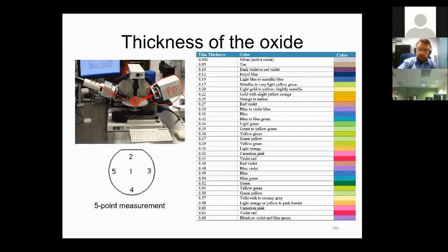But there are other ellipsometers, in that case you don't have to do this, but you might have to enter an initial estimate, a guess, as the user. So you put your wafer next to charts like this, and then you try to associate the color that you see coming from the wafer with these color charts, and then you say, okay, so it might be 0.34 micrometers. So I'm just going to enter that guess and then let the ellipsometer take care. If it is in this vicinity, it will give you the result in angstrom level. So that's as powerful as it is, the ellipsometers.